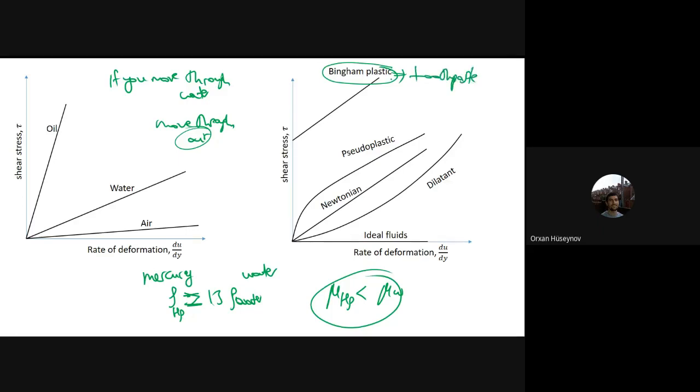And the non-Newtonian fluids are also classified as being plastic, pseudo-plastic, dilatant. Okay, we'll talk about in our next lectures. But toothpaste is non-Newtonian fluid. If you ask why, so if you squeeze the toothpaste, you can feel that till some point the toothpaste doesn't flow. Okay, till some point the paste is always there, but after some amount of shear stress, the paste starts to flow. Okay, till that point the paste doesn't flow, but after some amount of force, the paste starts to flow.